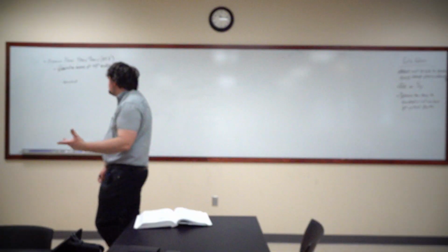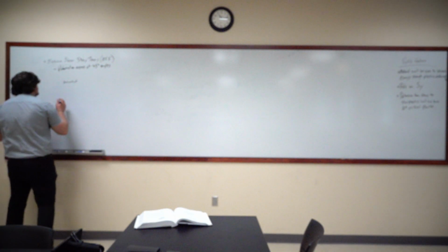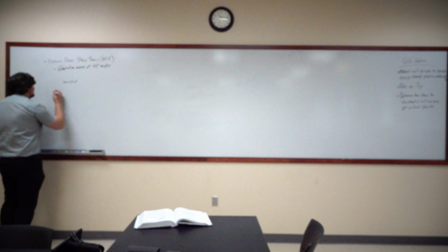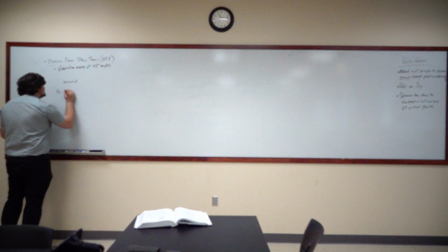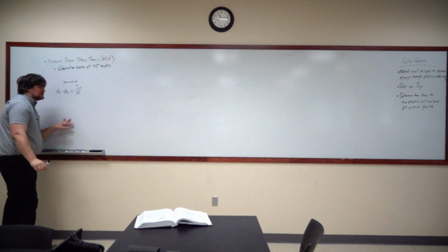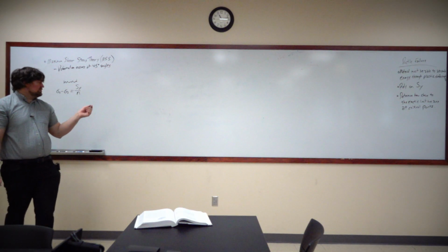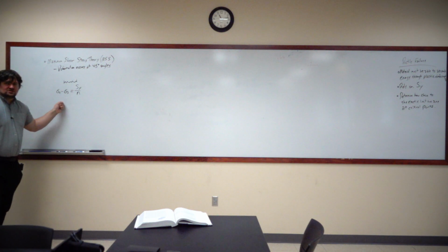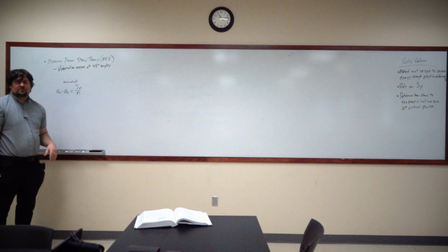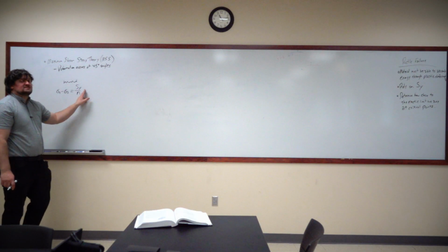But we end up with one basic equation that is used to determine static failure, and that is sigma 1 minus sigma 3 equals Sy over n. Okay? This is the equation that we use. We already talked about how to determine sigma 1 and sigma 3; I'm not going to go back over that, as that is a topic for a previous class. Sy is a material property.